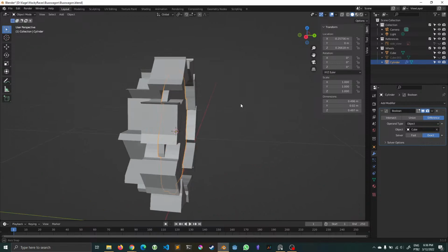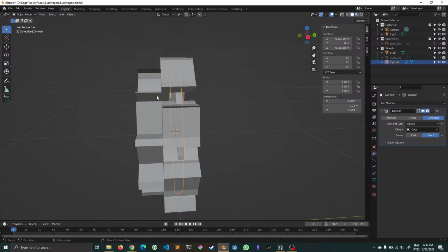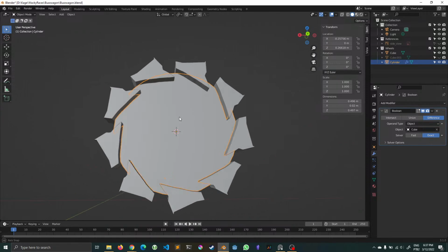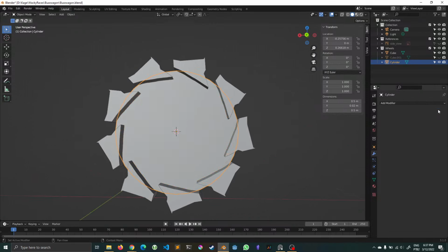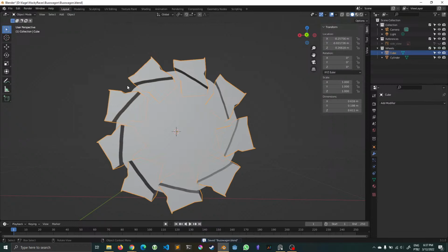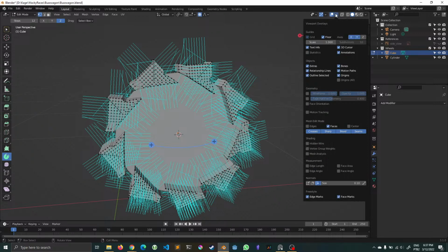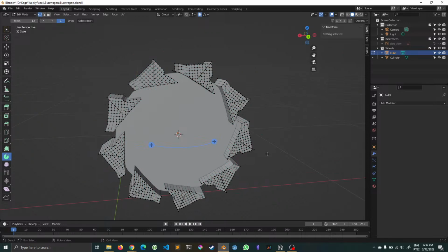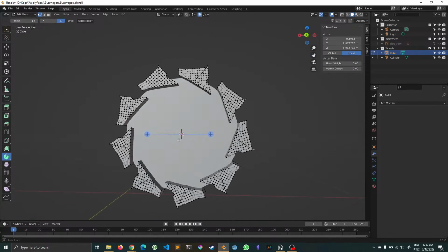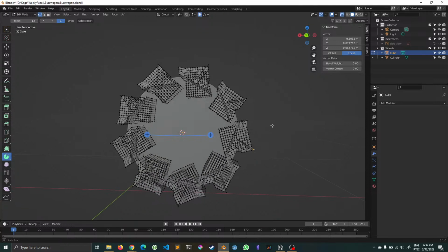Okay, so here is what I am going to try to do. I'm going to just try to fix my completely deformed cube here. And maybe after we fix it, things are going to actually work. So let's go to our cube. Let's go to edit mode. We don't need to see the normals. So let's turn this off. Okay, I'm going to delete all the others.